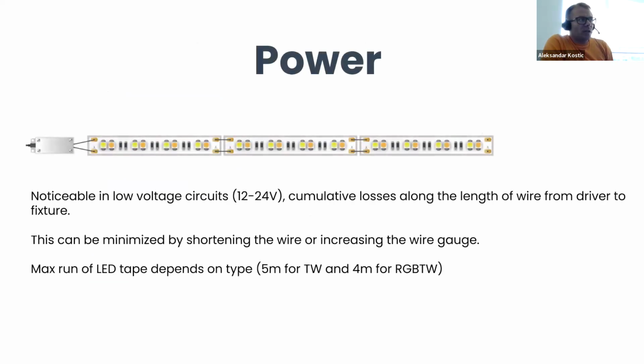Okay, so regarding the power, it is also important how far our power supply is from the LED tape itself. That means how long are the wires connecting the power supply and the LED tape, because each wire will introduce some voltage drop, which is higher as the length of the wire is longer.